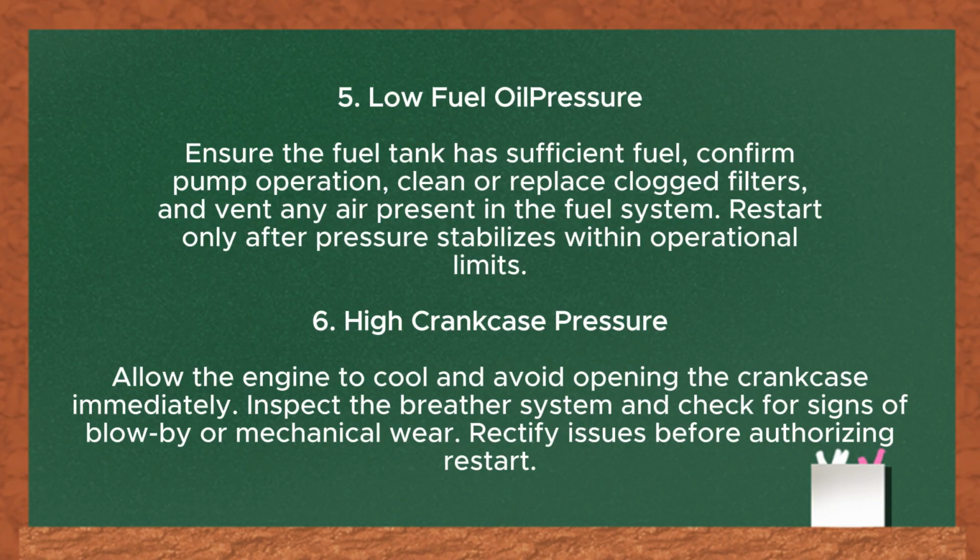And the 5th, low fuel oil pressure. Ensure the fuel tank has sufficient fuel. Confirm pump operation. Clean or replace clogged filters and vent any air present in the fuel system. Restart only after pressure stabilizes within operational limits.